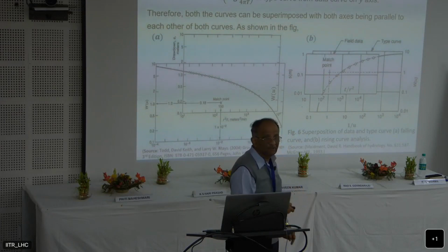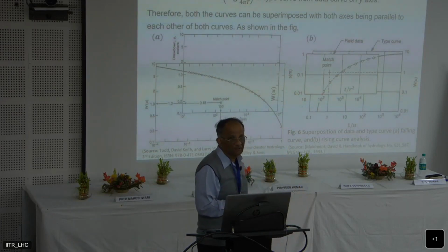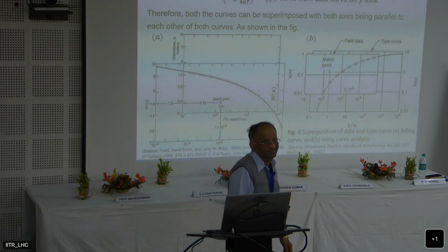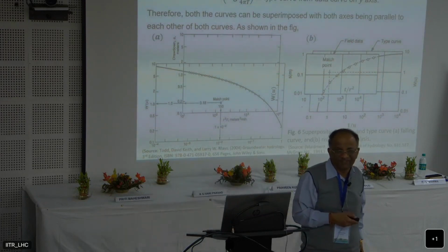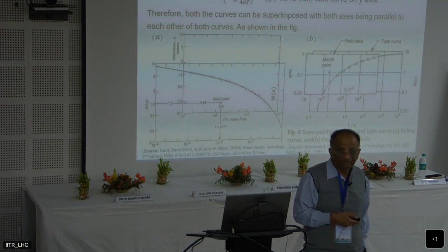Well function is nothing but W of u as such. What is meant by u, sir? u is r square S by 4Tt. There is no name given to it; I think there is no name for it. So u is just values going from 0 to infinity, and W of u is a fixed function which gives a value for different u values.